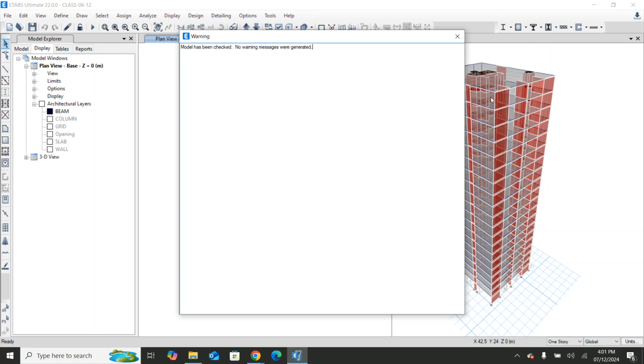But mistakenly you didn't see that and you draw the columns again over there and you copy paste into all the floors. So many frames will be there, and all these frames you have to correct again, which is the same effort as creating a new model. So when you create the first story and you plan to copy and paste it, just make sure that there are no issues on your first story, then copy and paste it. Okay. That is it.